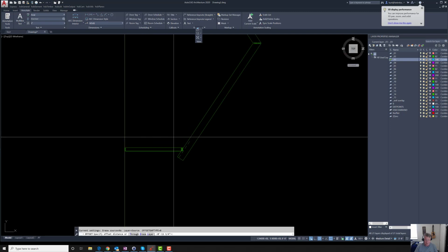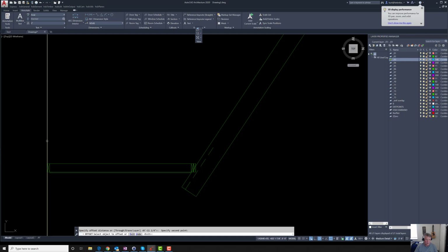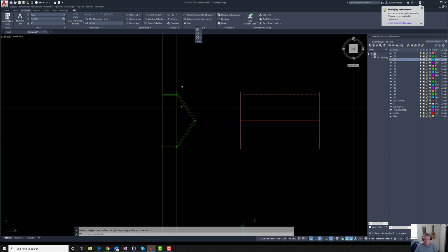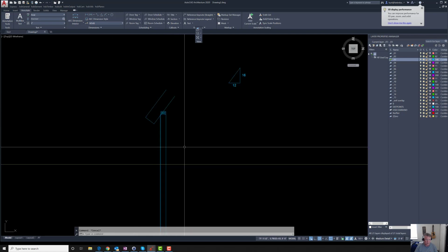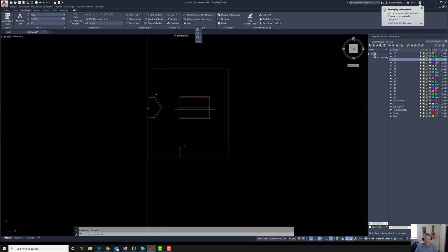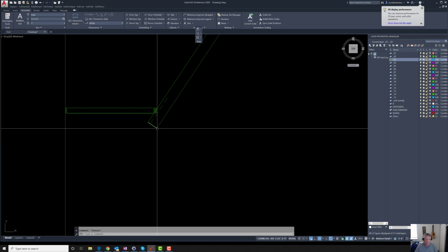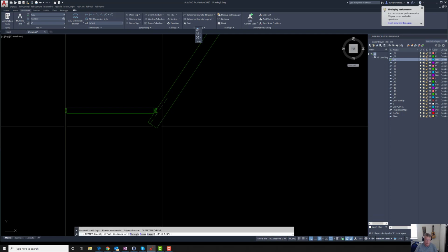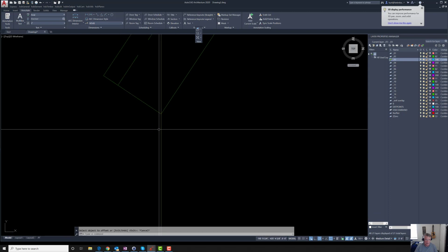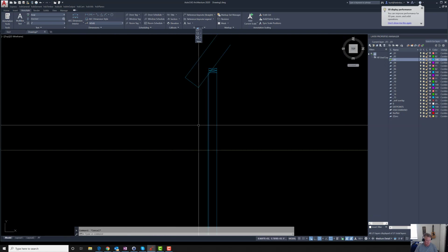So we will offset again, and this time we'll use this 0 line, or the floor line. And what that does is allow me to transfer heights from one view to another view over here. So now, and I did it incorrectly because we don't really want to use the wall height. What's important to us on this particular project is making these top fascia corners meet. So what I want to do is offset the distance from the tip of the fascia to the 0 or floor line up.